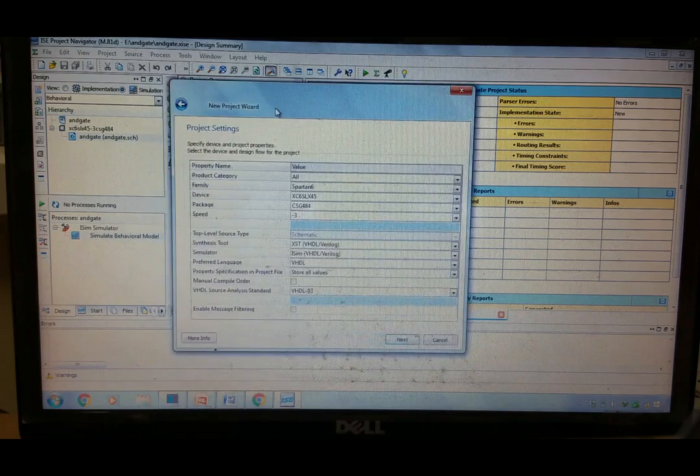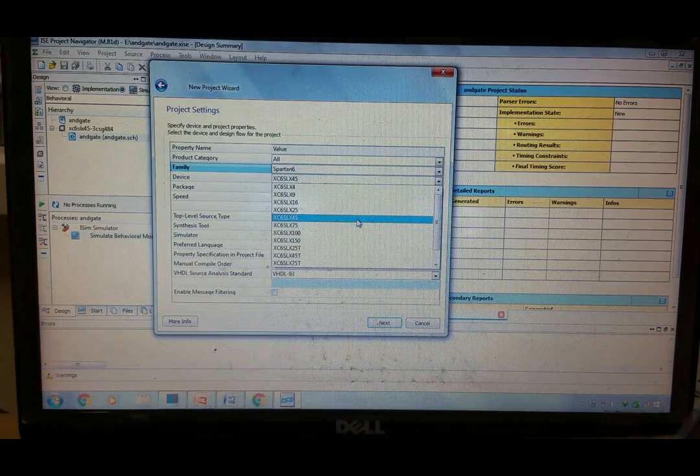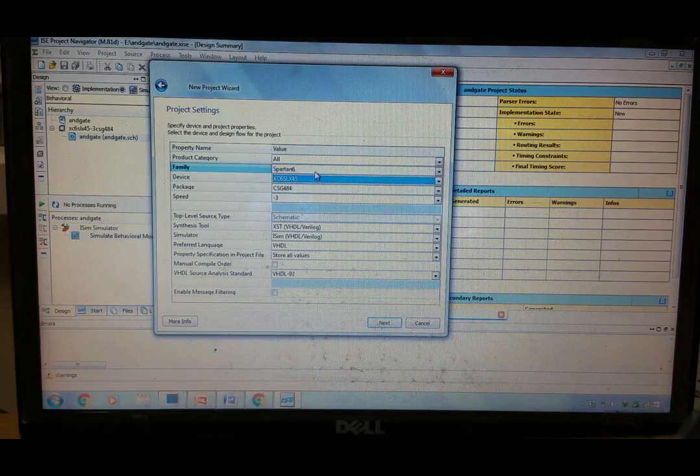So this new project wizard will open. In this new project wizard you have to mention the family, the device and the package of the FPGA which you will be using to burn the program. In this video I'm not demonstrating how to burn or program the FPGA using this code, but if you have an FPGA, then you should select the family of the FPGA here, and over it the device and the package will be mentioned. You should select that here. What I have is a Spartan 6 FPGA with this device and this package.